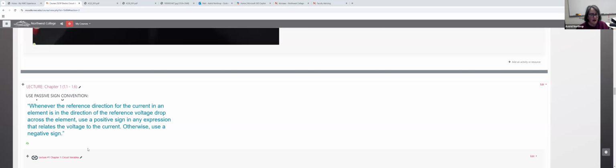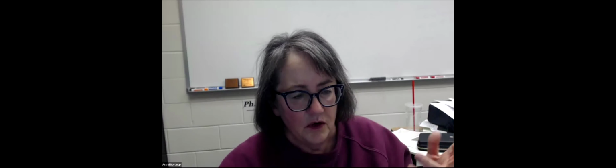It can be a little bit confusing for a couple of reasons. One of the reasons is that if you have familiarity with electrical appliances or elements in real life, we don't really call things negative or positive in this way. Often we just say something makes power. We don't talk about absorbing as being positive; we talk about delivering power as being positive. But in order to make the math work, it becomes crucially important that you follow the passive sign convention.